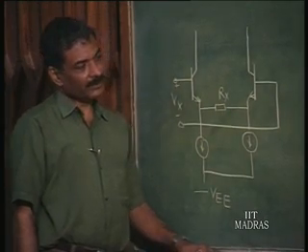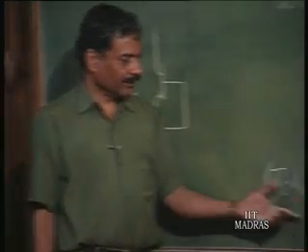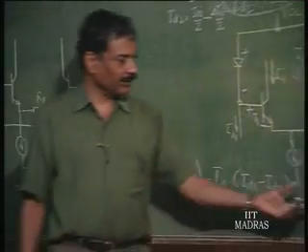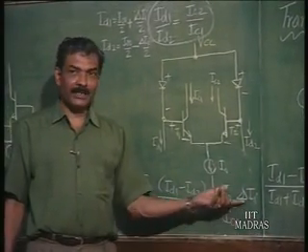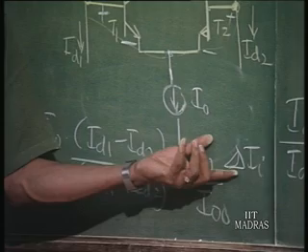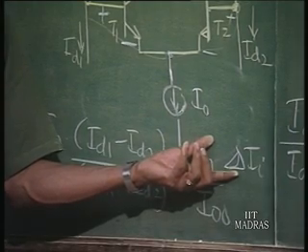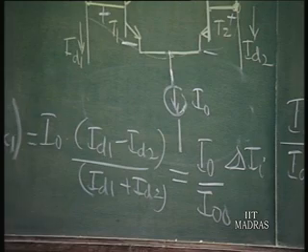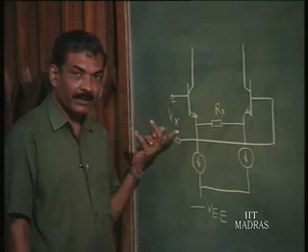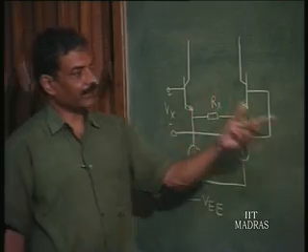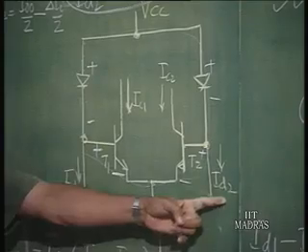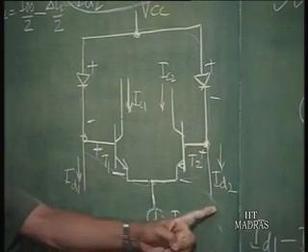So, even though this Gilbert's gain cell tells us that the output differential current is input differential current times I naught by I naught naught, there is some kind of multiplication taking place in terms of currents, but we would like this to happen in terms of voltage. So, we need a voltage to current converter, but it should be a voltage to differential current converter, which is required as input to this gain cell, ID1 and ID2.